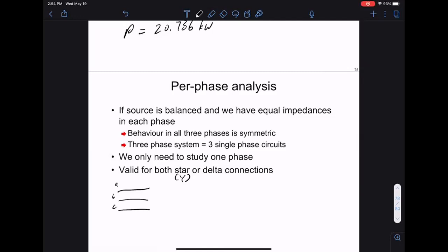When you look at high voltage transmission, if you're ever driving on the highway you can take a look, the lines will run something like this. This is A. We'll run for a while, and they'll actually change position. This is A, this is B, this B will come up, and this is C. So the 3 wires will be transposed this way, and on average this makes them all symmetrical to each other. We take a lot of effort to make things symmetrical in practice. Having phase balance is very important.